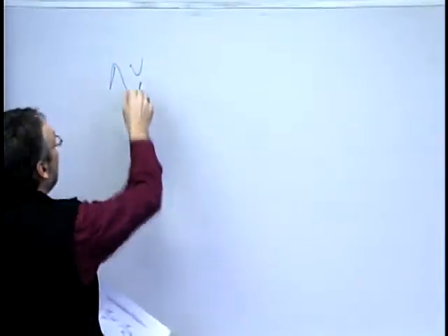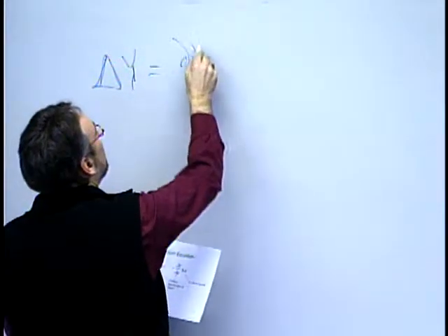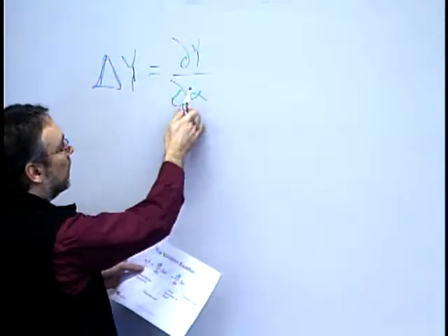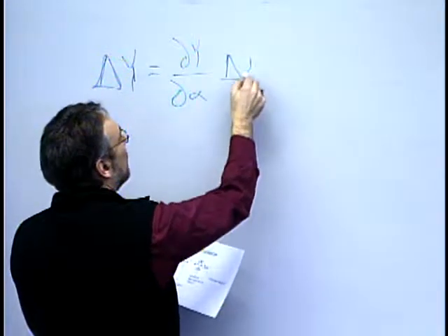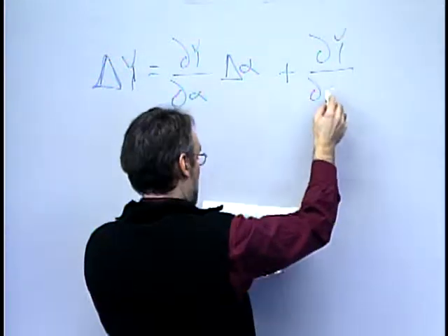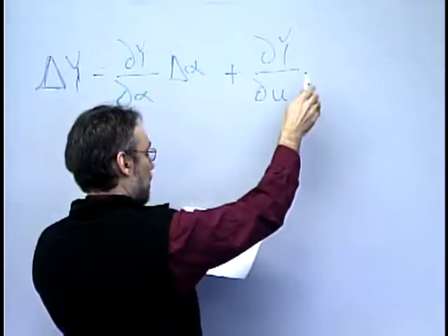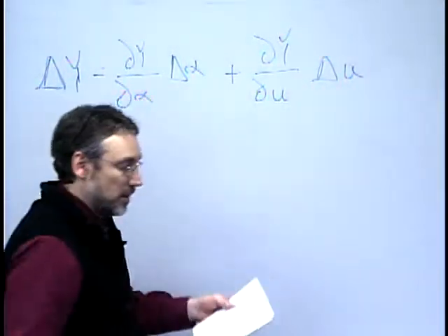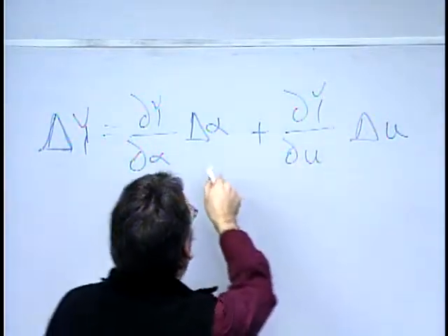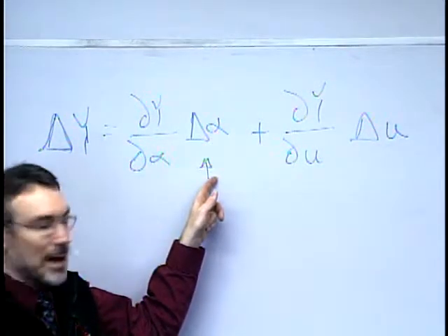We said that our deviations in our output y we can often characterize as some component that has a sensitivity to disturbances in our process parameters and those disturbances, and some component that relates to our controllability when we make small changes u, the control inputs. And we said that, among other things, maybe some of our input feedstock may be delta A's, right? Changes in the parameters.